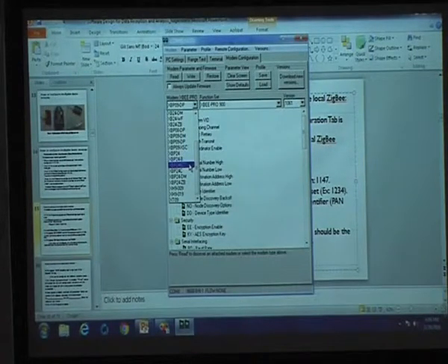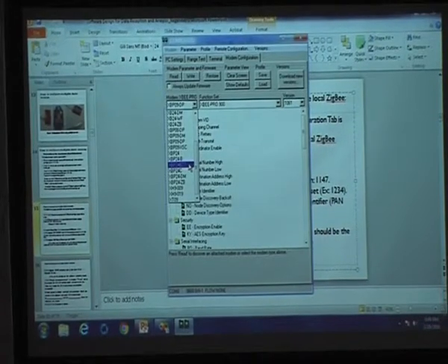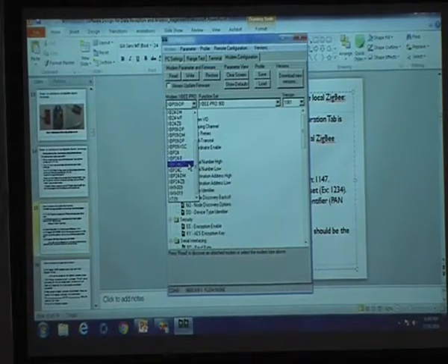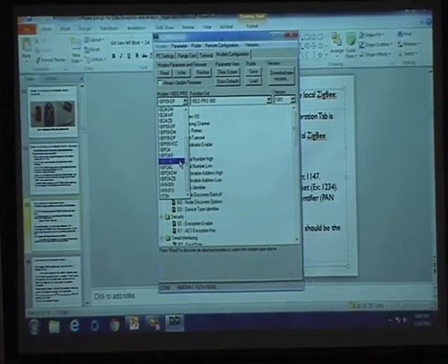The one for which you are now trying to set up the wireless sensor network is mesh networking. Depending on the topology, you need to use different sets of modules. In order to set up the mesh networking topology, you need to select what type of modem it should be and the functional set of that corresponding modem. There are two different values. This is what you call the modem type, and this is the functional set and the version.